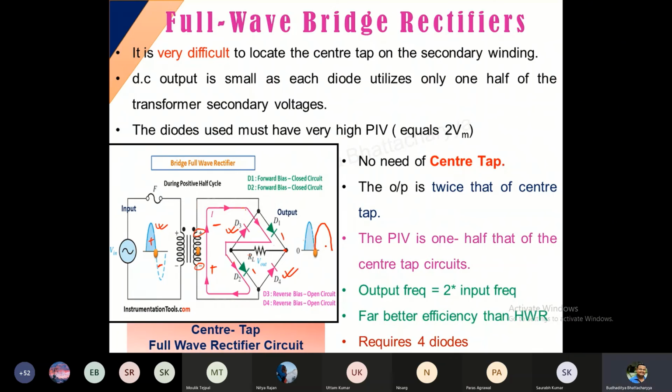So it is very similar to the center tap that I discussed. But the advantage is that you can see there is no such tapping over here. So no tapping is present. So the complexity regarding the tapping of the circuit is not there, which is a huge advantage. Got it? So in that way, the rectification is done, full wave rectification is happening, but without the central tapping.